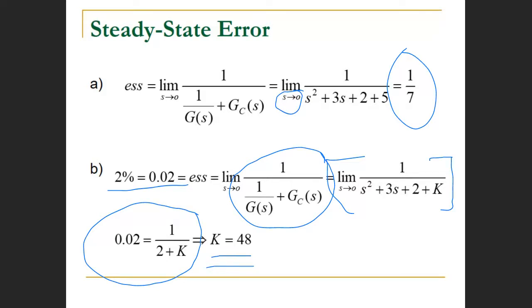All right. Now, you recall what happened in the plot that we did earlier. As we increase k, we notice that the steady state error decreased. All right, we notice that the steady state error decreased. But did you notice also, let me ask you, what else did you notice from the plot? Maybe it was obvious, I don't know. What is this from the plot? The settling time decreased. Settling time increase, sir.